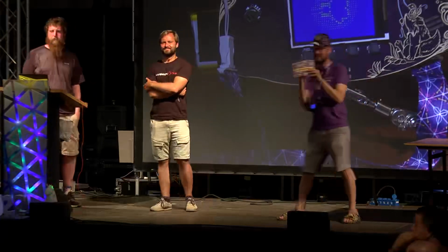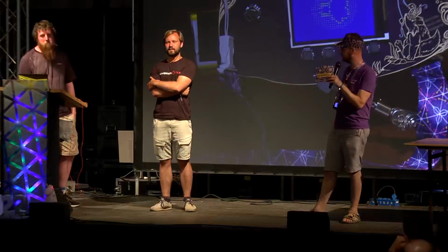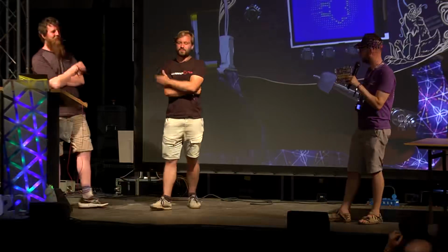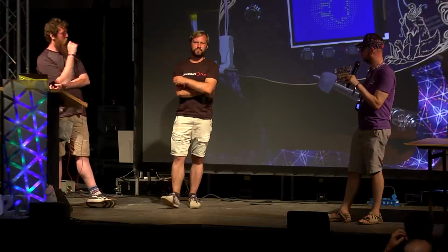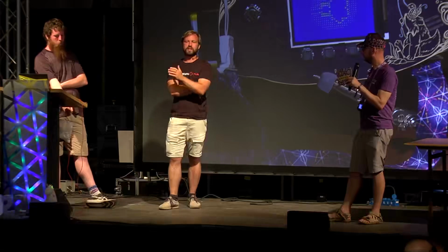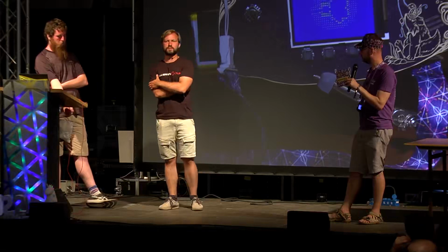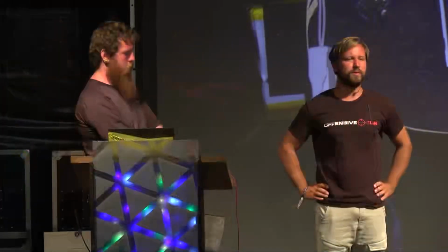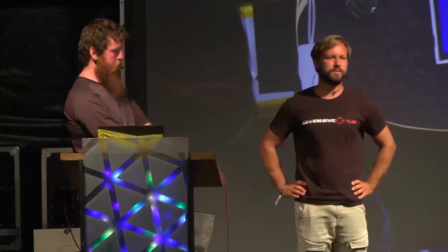Do you have a favorite fault injection method? Personal favorite? One of the reasons why I used EM is because it is quite easy. We don't really need to do anything with the target. We just have it as it is. We don't need to decap it, so there are no chemicals involved, no polishing. We just get it as it is, and we can start glitching. We don't need to modify power and so on. That's what we often use because of the simplicity.